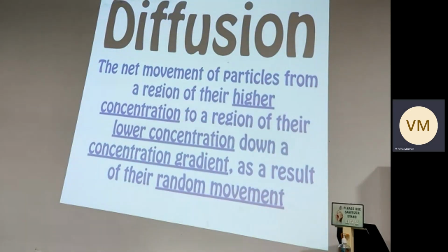So what does it mean if I want to put p-type inside the silicon wafer? What do I need to do? I need to put it in a chamber and create so much concentration of the surrounding that it should feel that the concentration in the chamber is higher than in the silicon, then it will go, right? So therefore I need to cover the remaining areas. I cannot do it selectively.